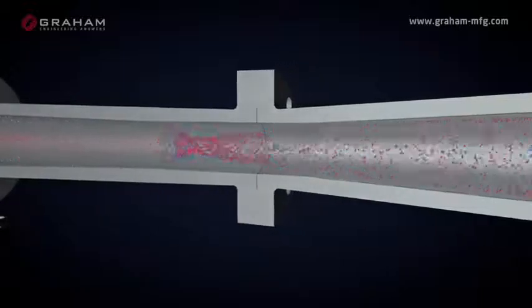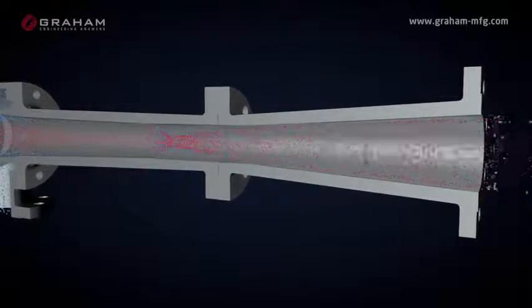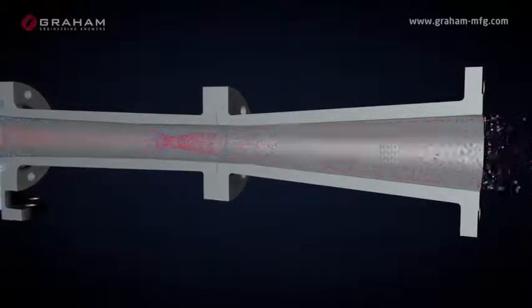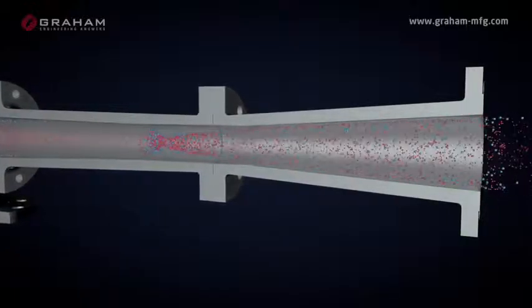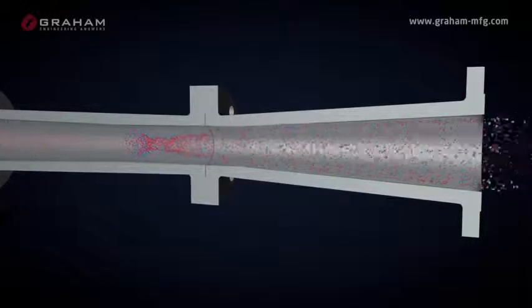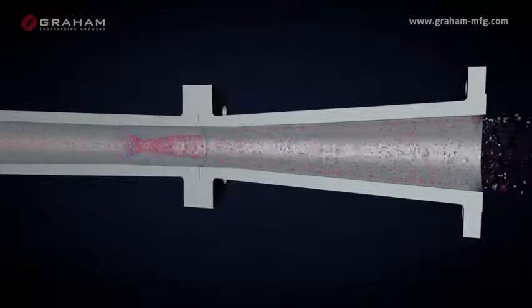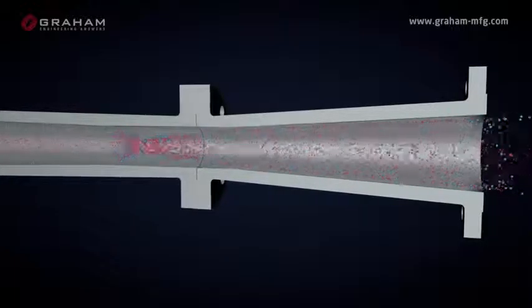The pressure is increased further in the outlet diverging section of the diffuser, where the subsonic mixture velocity is reduced as cross-sectional area increases from the throat diameter to the discharge diameter. Slightly less than half of the total compression achieved in an ejector is obtained in the outlet diffuser section through simple deceleration of the subsonic flow.